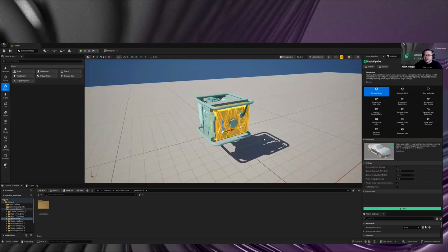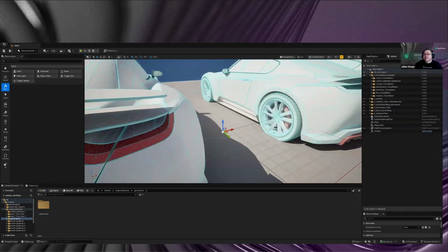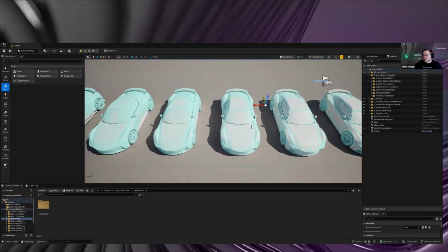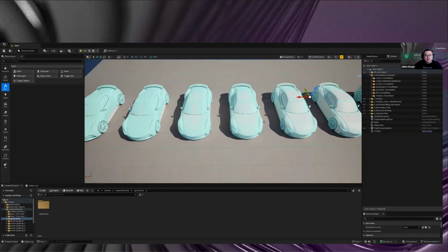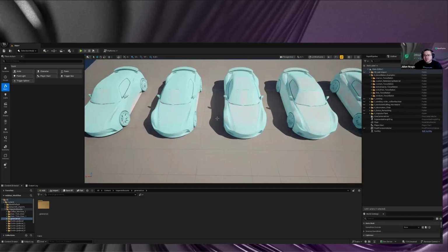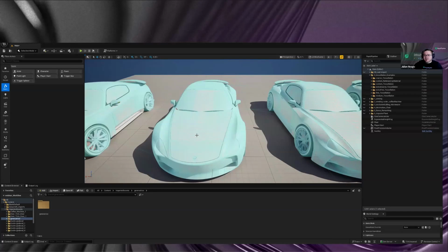Let me see if I can show that just a little bit. We have the different tessellation solutions. That's something I wanted to show anyways, and then we can jump directly into this use case and topic as well. So as you can see, we can go from the presets from very coarse all the way to very fine and have then a more high resolution distribution of faces. And the one here on the very left side, these two here, the other ones with custom tessellation. So I just increased the resolution on the custom side a little bit, something I just showed before.